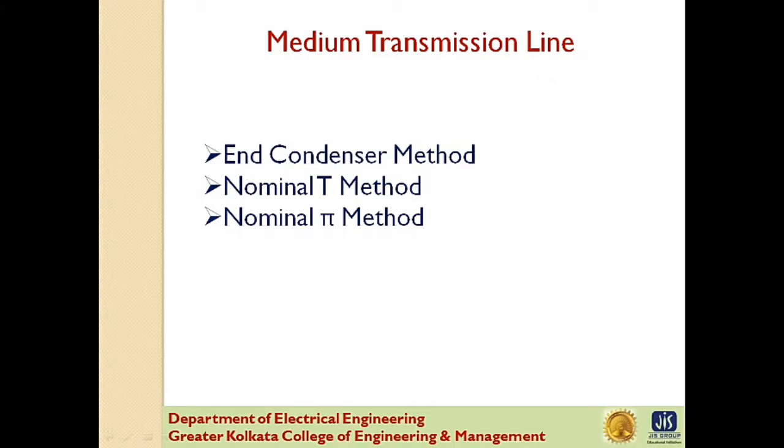Now, in the previous video, I discussed short transmission lines. In short transmission line calculation, the effects of line capacitance are neglected because such lines have smaller length and transmit power at a relatively low voltage, that is below 20 kV. However, as the length and voltage of the line increase, the capacitance gradually becomes of greater importance.